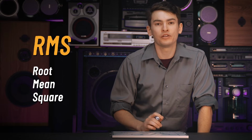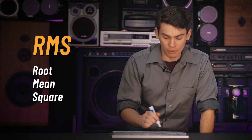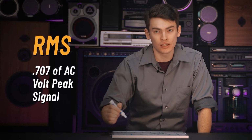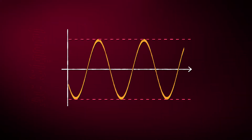RMS stands for root mean squared. The name comes from how you derive the formula, which is well beyond the scope of this video. All you need to know is that RMS equals 0.707 of the AC volt peak signal. To further clarify that, 0.707 of your voltage peak lies around here. That means about 70% of your signal can be described with whatever RMS voltage you calculate.